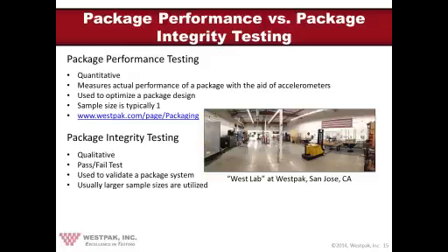So the topic is package integrity testing, but it's not to be confused with package performance testing. These are two different types of tests that are done in a laboratory. Package performance testing is often quantitative and is used to evaluate specific functions of a package. This can be evaluation of the ability of the cushion system to mitigate shock, done by mounting accelerometers and doing a drop test to evaluate cushion performance.